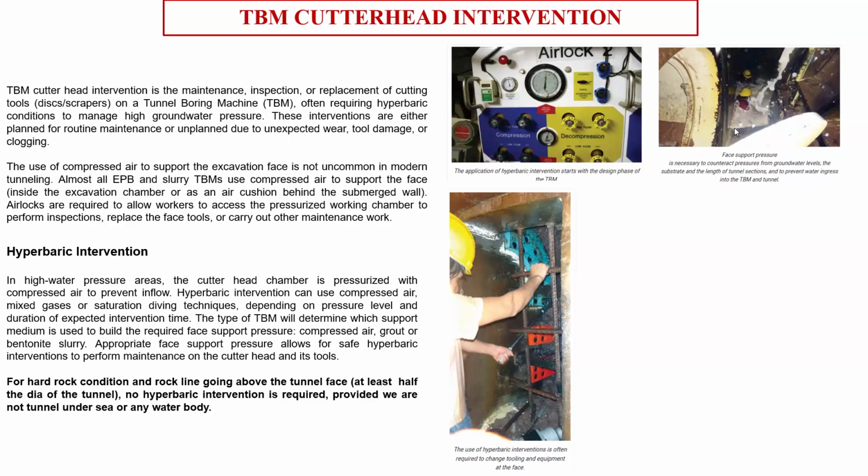Even we can see that some segments are getting cracks also, and these cracks are sometimes out of tolerance because all our segments have a crack limit of 0.25 mm. So it can happen that the segment has gone more than 0.25 mm. So what will be the rectification process?